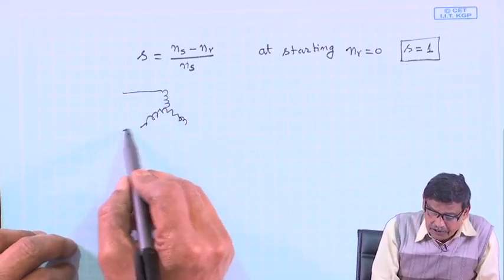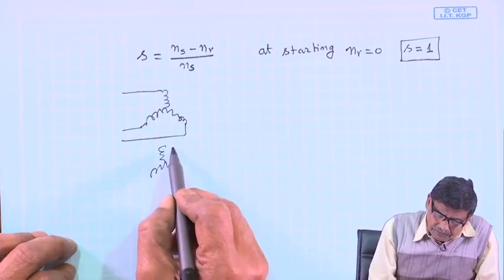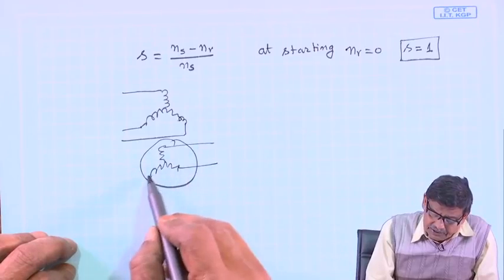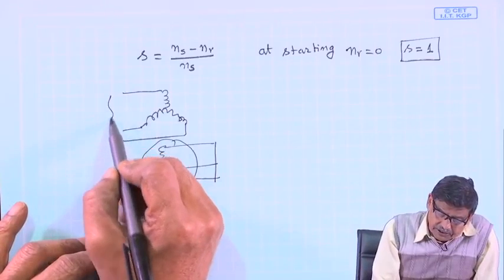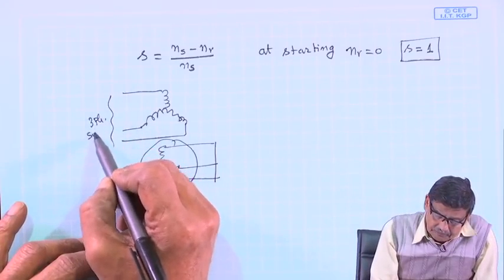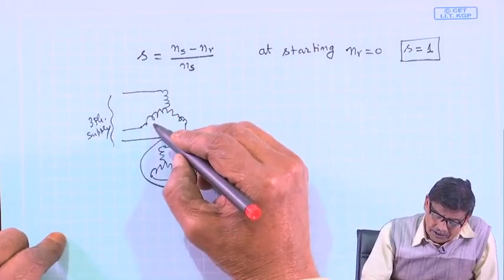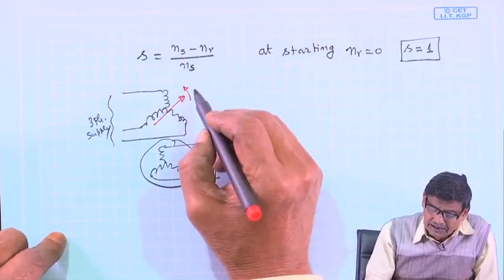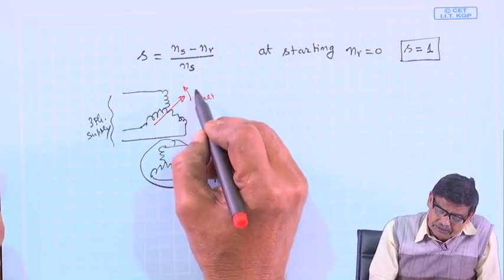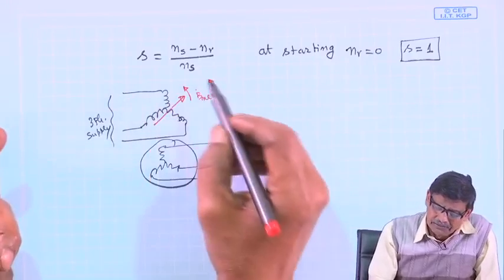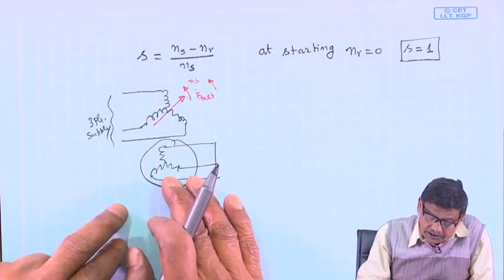So, these are the 3 phase supply, and this is suppose the rotor, and these 3 terminals are shorted like this, and I have energized with 3 phase supply, and I know with proper phase sequence I can create, with rotor closed, ultimately it is B net, or B s, which is moving with synchronous speed Ns with respect to a stationary observer, and rotor is yet to start.